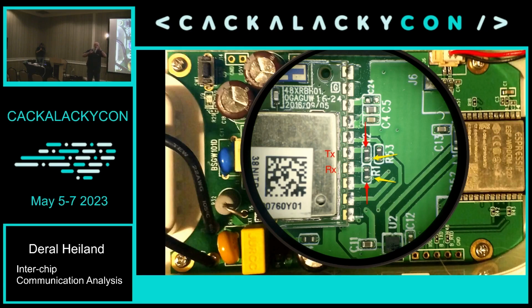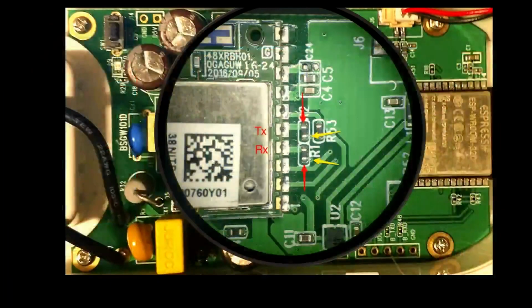Remember, we have communication going both ways. So there's transmit going both ways, just transmit and receive depends on what direction it's going in. So in this case here, we want to tap into the circuit between where that TX is and where that resistor is, a very small space. I started thinking, hey, let's just redesign the board slightly and make this a little easier.